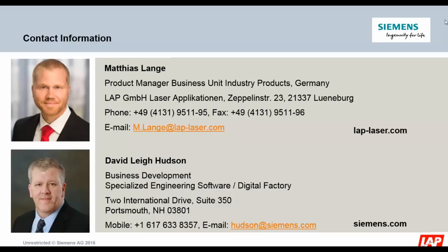Okay. So, as I was talking about earlier, one of the experiences that we've had is that for fiber placement, minimum course corners, things like that, are not always achievable with particular machines, and there are a couple of solutions that can occur. There can be a design for manufacturing solution, which is something that FiberSim supports, or we have customers that will stop the machine and manually lay up things like minimum course corners, and so they use laser projection in the middle of that process.